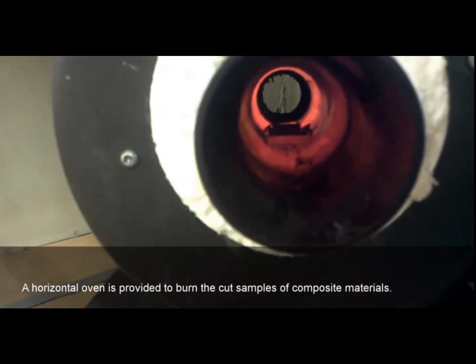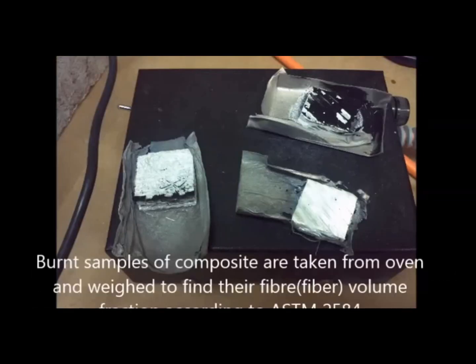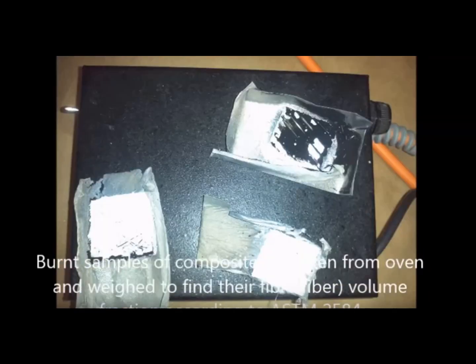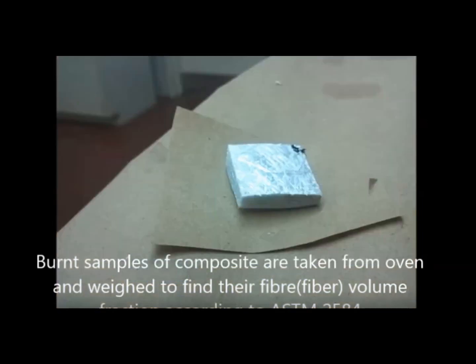In this, as you can see from the video, a horizontal oven has been provided to perform the burn test of a composite sample. The composite tabs are cut in the dimension 20 cross 20 mm, and then they will be put in a ceramic crucible for performing a burn test. Thereafter, burnt samples of composites are to be taken out from the oven and weighed to find their fiber volume fraction.